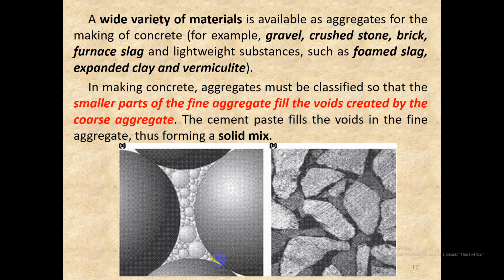The reason for using two different aggregate types is that if the aggregates were combined at source and then transported to site on a lorry, say, much of the sand would filter through the gravel voids to the bottom of the pile, so concrete made using the top of a pile would have different aggregate than concrete made using aggregate recovered from the bottom of a pile.